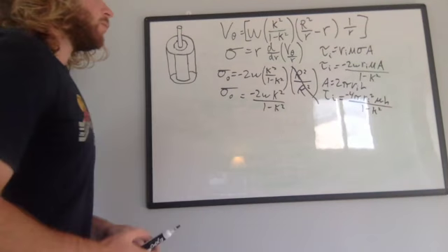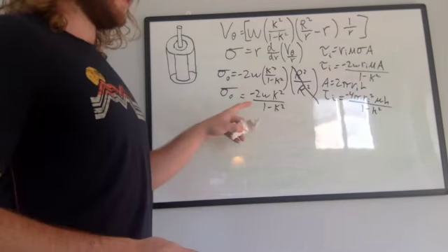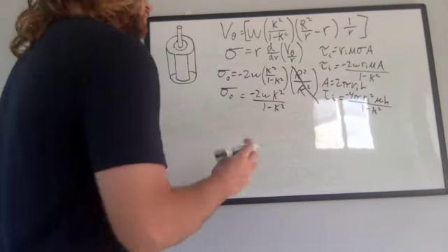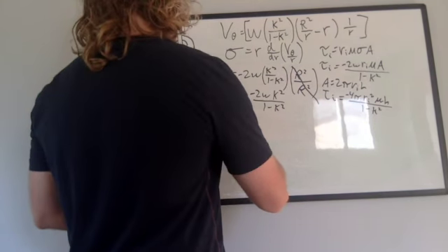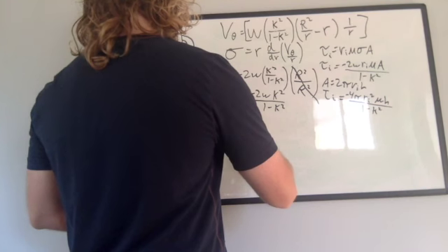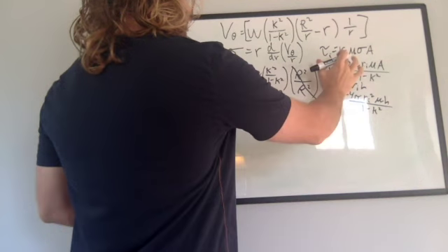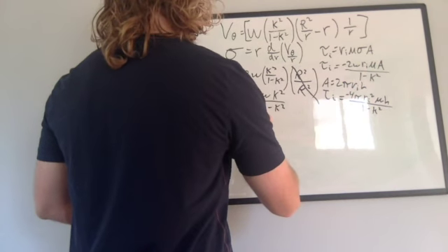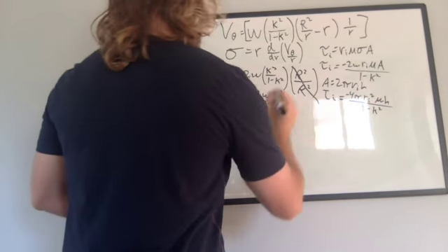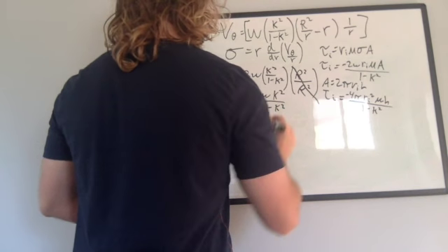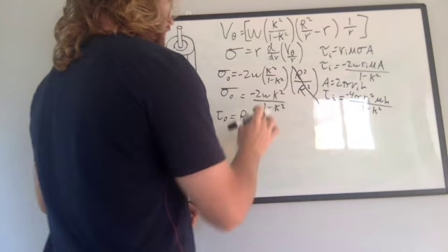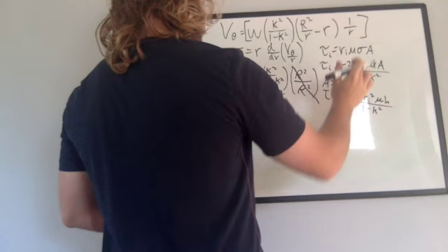All right, and now we can use this to go ahead and solve for our torque at the outer circle, or cylinder, excuse me. So our T at the outer is going to be equal to, again, this is going to be big R this time, multiplied by the viscosity. And then we are going to have this expression right here for our shear rate.